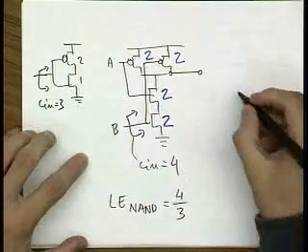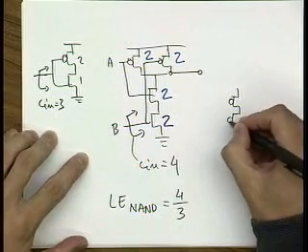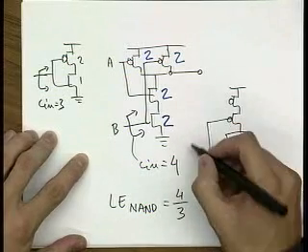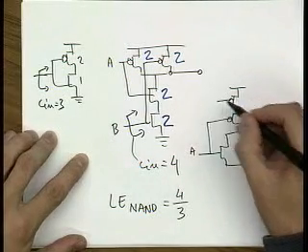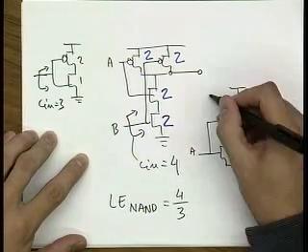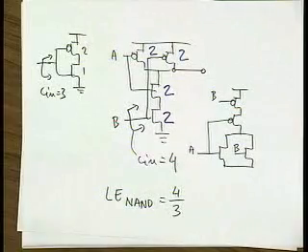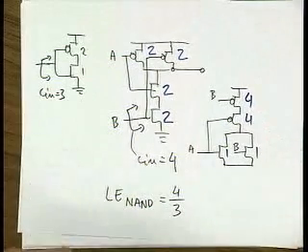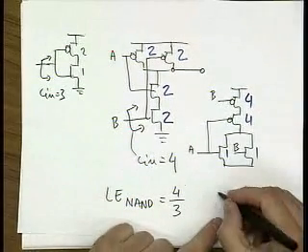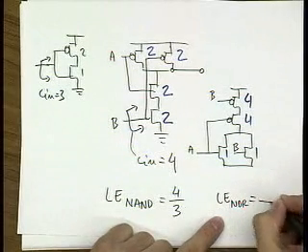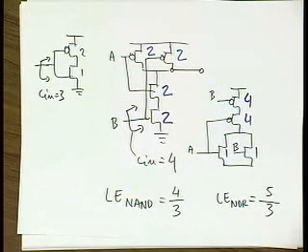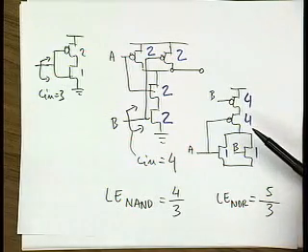Okay, so let's do the NOR gate. So in the NOR gate, we also have 2 inputs, A and B. See, this is B, this is B. And then the sizing of the NOR gate would be 4, 4, 1, 1. So the logical effort of a NOR would be what? 5 over 3, correct. So you see that you can sort of understand which gates are good. So you see the NOR is not as good as the NAND because it has a stack of these PMOS devices.